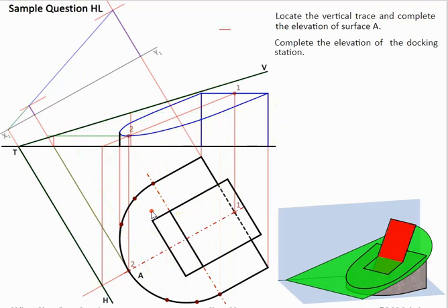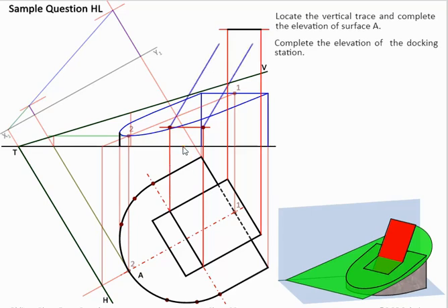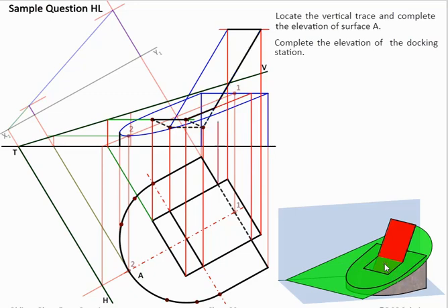Now we have an opening here. Next thing we're going to do is construct up this section here. We're given a height for this in the question. These points are brought up here. So this here is our face now sloping at the required angle. Now the next thing we're going to do is draw the opening section here, so we have the opening section that we can draw in heavy. So this is our drawing now more or less complete, put in heavy here.